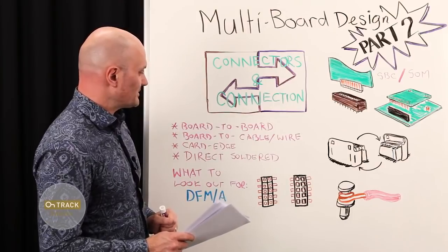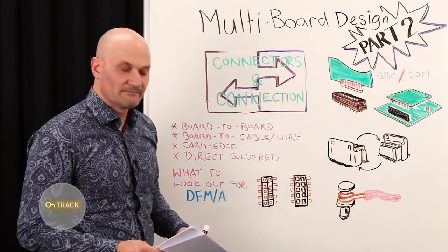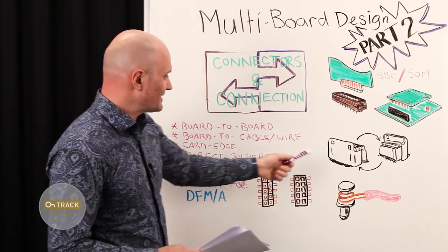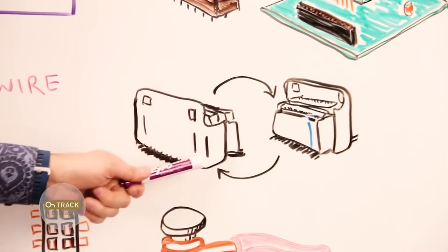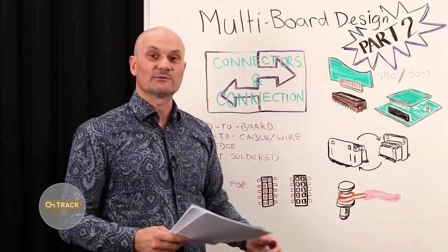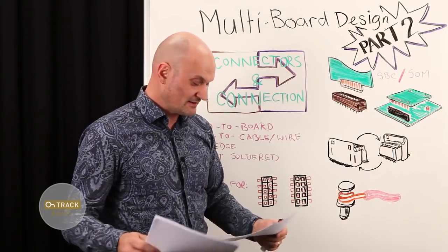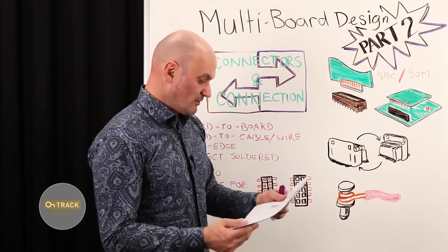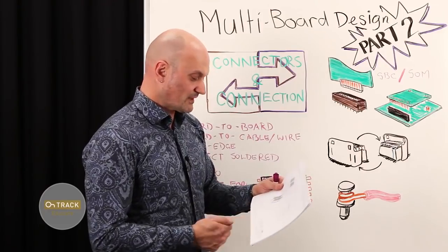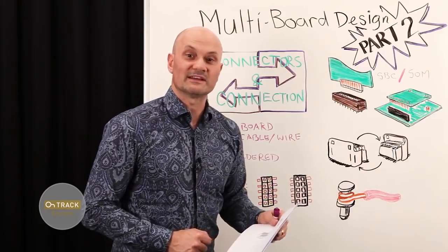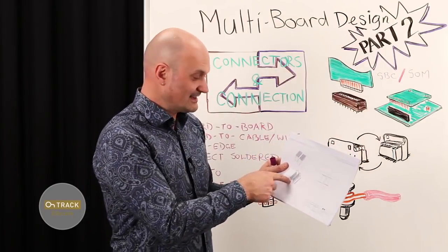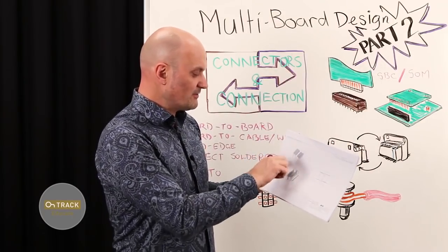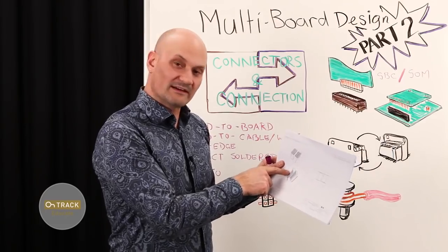Another kind of connector, which is becoming more popular, is the hermaphroditic connector. And I've got a pretty basic drawing I've attempted to do of one of these here. But again, I'll switch over to this TE connectivity data sheet that shows a pretty good diagram of how hermaphroditic connectors actually work. And we have the exact same part, but when you flip it over, it mates with the exact same part.